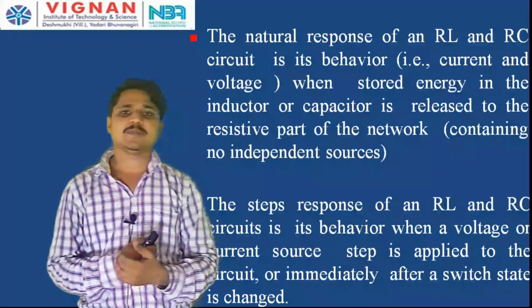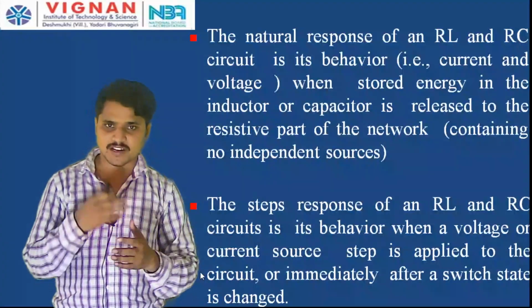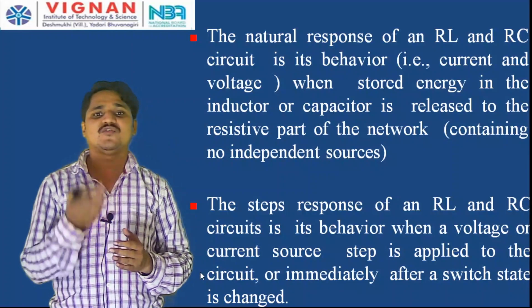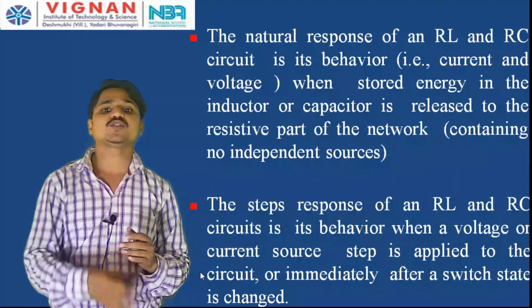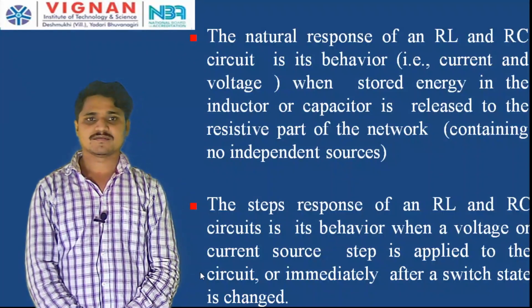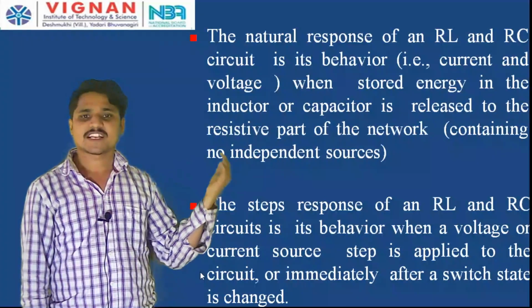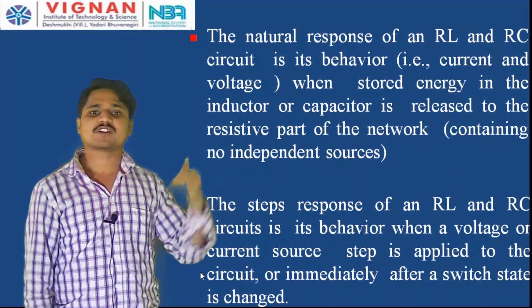Now, what is meant by a natural response? The natural response of an RL and RC circuit is its behavior when the energy stored in the inductor or capacitor is released to the resistive part of the network. Otherwise, you can say it is the response of the RL and RC circuit immediately after the switching action.